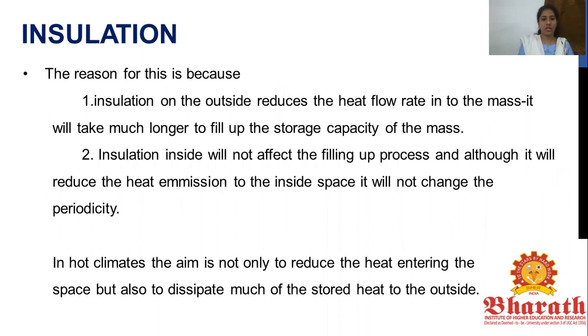So what happens is that the insulation on the outside reduces the heat flow into the mass and it will take much longer to fill up the storage. It's on the outside, so it becomes like a barricade to let the heat in. If the wall is already heated up and then you add an insulator, the effect is very little, whereas when it stands outside and stops the heat from coming in, its effect is increased.